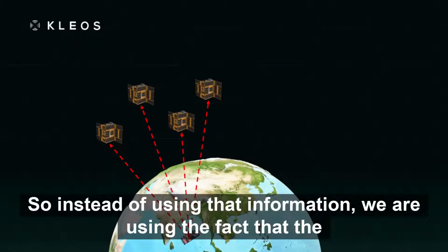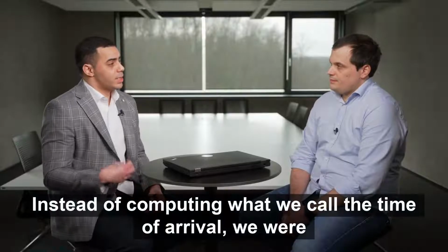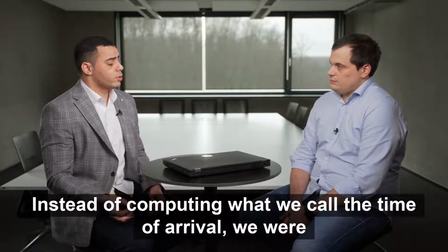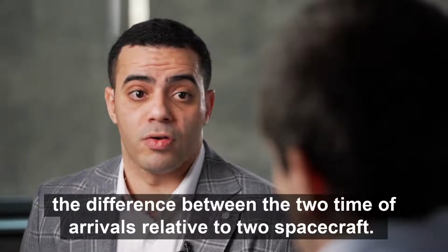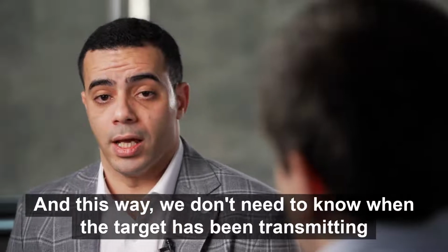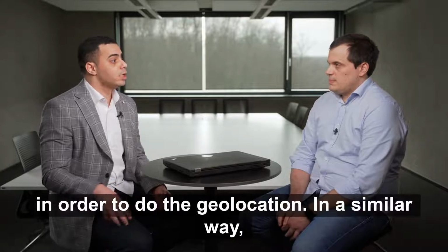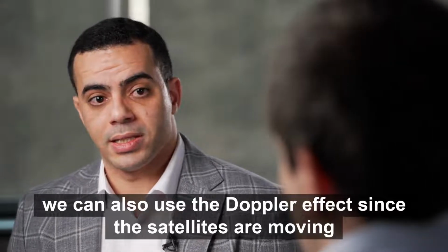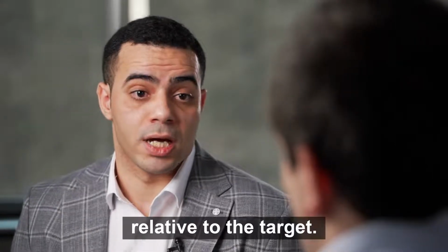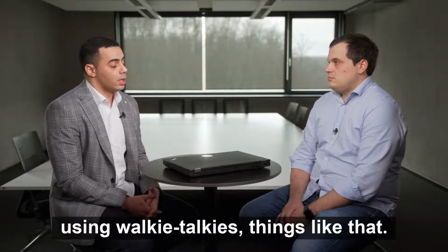So instead of using that information, we are using the fact that the signal is being received by multiple spacecraft at different times. So instead of computing what we call the time of arrival, we are going to compute the time difference of arrival, which is basically the difference between the two times of arrival relative to two spacecraft. And in this way, we don't need to know when the target has been transmitting the signal in order to do the geolocation. In a similar way, we can also use the Doppler effect since the satellites are moving relative to the target. So when we talk about target, we're talking about ships, users that are using walkie-talkies, things like that.